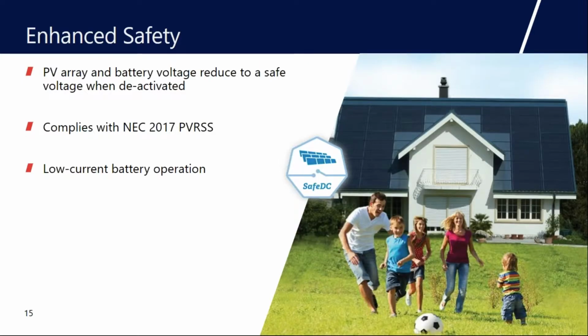Safety is always near and dear to my heart. With SolarEdge, our optimizers operate underneath every single solar panel. So when you shut down the inverter or the system, the optimizers go to safe DC mode. That's 1 volt per optimizer in series, so if you have 20 modules in series, that's 20 volts.